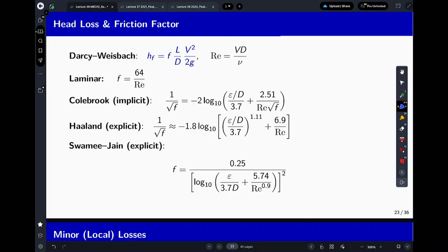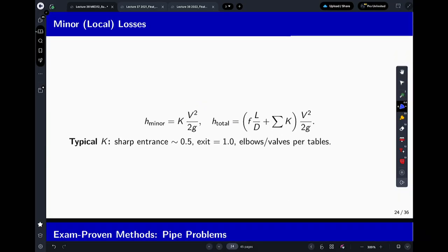There are two other relationships that I talked about in the lectures, about 5 or 6 lectures ago, so lecture 30, 31, somewhere around there, about the problems with Swamee-Jain for Q and D calculations. Q and D calculations are also there, but I would avoid those for now, unless you're absolutely certain that you have the correct physics for the Swamee-Jain in those explicit relationships.